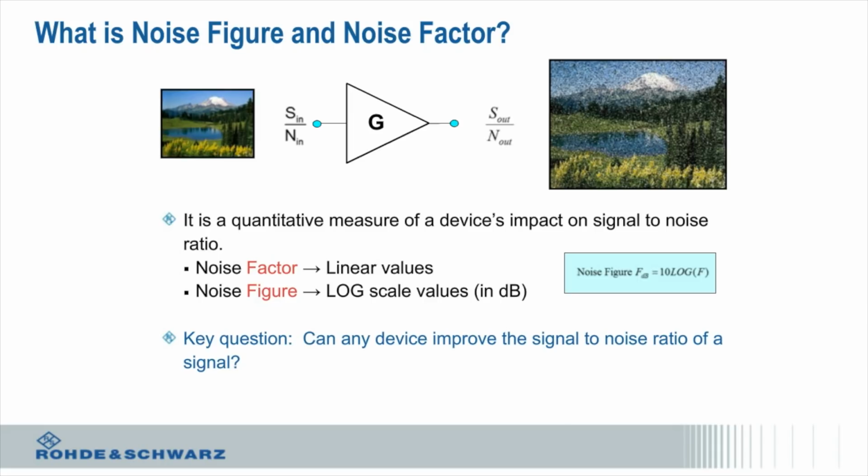You might find, if you're new to this, when you first start playing around with dBs and you take 10 log of some ratio, you'll be going back and forth, but you actually find when you get good at it that you want to just live in the dB world. Because the nice thing for dBs is you actually do everything by adding and subtracting. So where you have something like an amplifier that has a gain of 30 dB, that's a factor of 1,000. So instead of multiplying things by 1,000, you're just going to add 30.